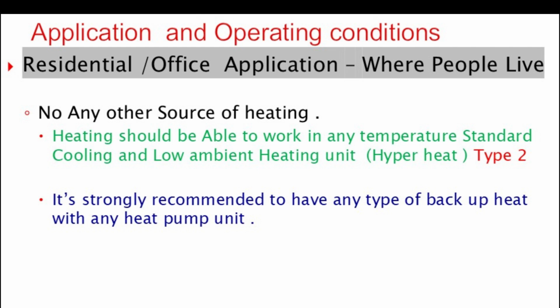Mitsubishi's Hyper Heat pumps retain 70 to 80% of their capacity at minus 25 degrees Celsius. However, it's highly recommended to have a backup heating system. As mentioned earlier, you'll need a Type 2 heat pump unit for this application.